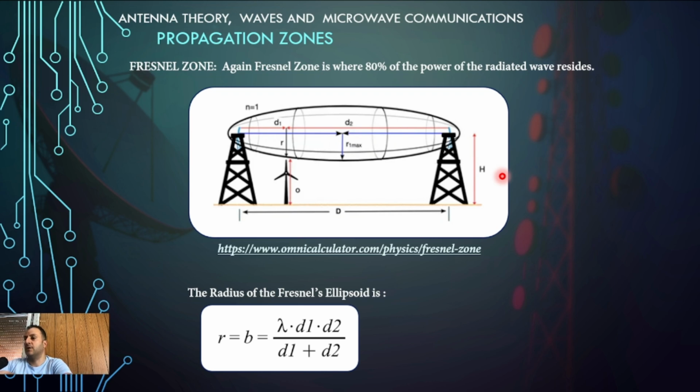That's interesting. By the way, the maximum radius is the trough of the ellipse. Perhaps trough is not the accurate word to say, but this is the lowest point at the bottom of the belly of the ellipse between these two microwave points. So again, R max is equal to lambda D1 D2 over D1 plus D2, lambda being the wavelength.